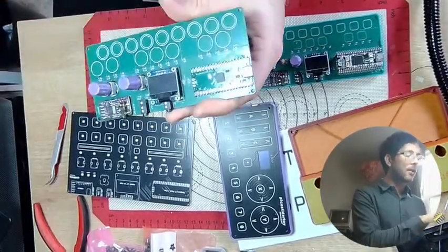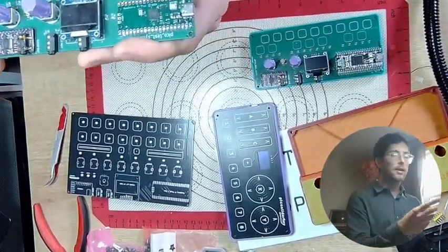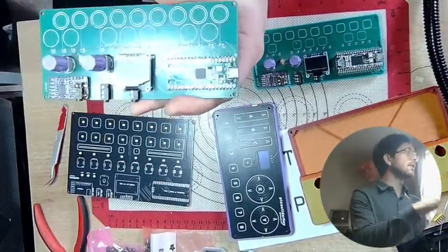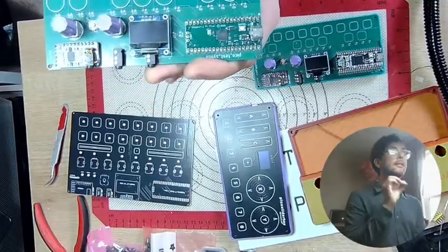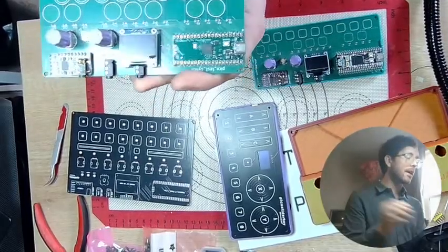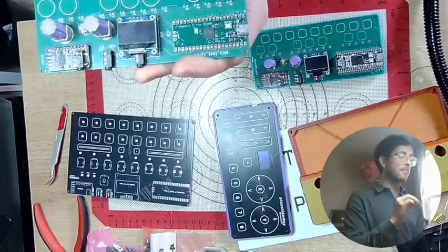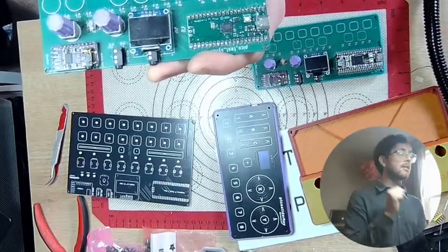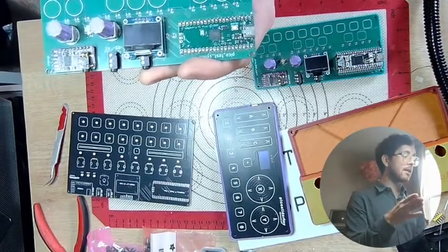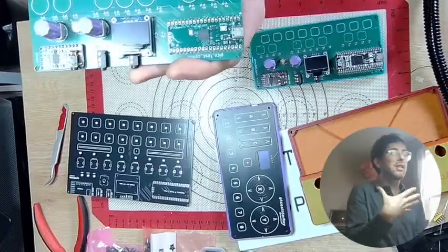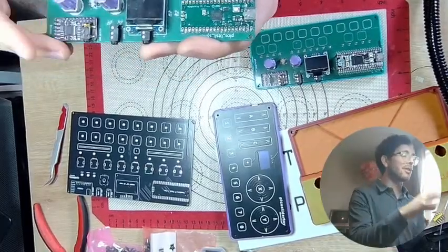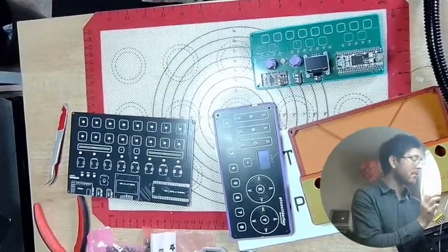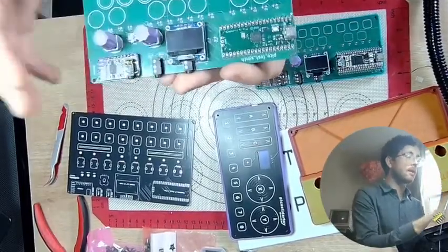Anyway, the Pico here is kind of controlling everything. It's got CircuitPython on it. And then we also have this I2C display, an SSD1306, which is a little OLED. These are really common. You'll notice in some of the other stuff we're going to look at, it's actually going to use SPI for the display, and there's a little bit of a performance boost there. It's nothing crazy. And then we have some MIDI in and out with some discrete components you can't really see. In fact, it's hidden underneath the display, but it's cool.